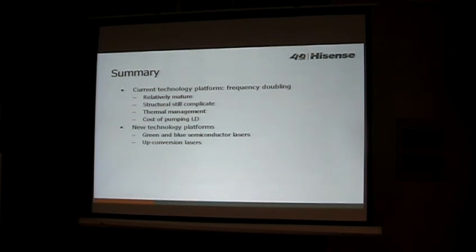Like I said, with a historical perspective, almost every year the wavelengths we need take 10 years to work out. But I think it's still possible, because now a lot of people put a lot of effort into getting blue or green semiconductor lasers. For example, if we use gallium nitride semiconductor compound to do that, the problem is the mismatch between the epi layer and the substrate layers. Now people are trying very hard to develop some material growth technology to grow a buffer. If they are successful, then this defect will be gone. Then we get this green laser.